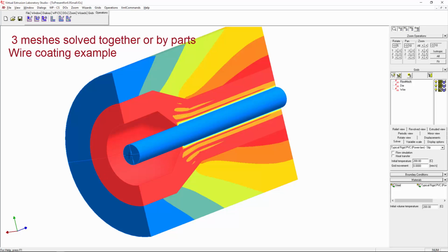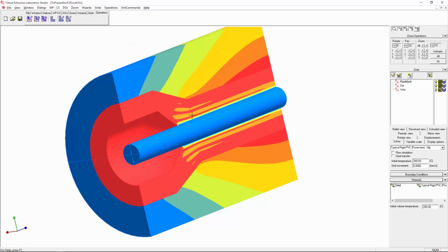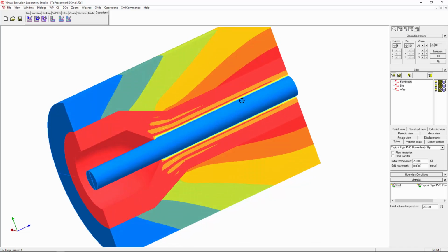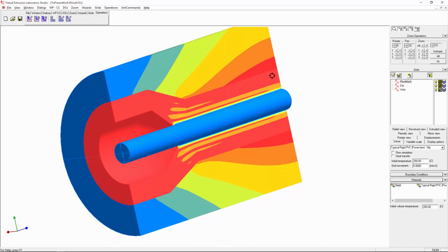Many companies preheat the wire, some companies don't. It is also very important whether the wire has a large heat capacity, is moving fast and is big in diameter, or has a small capacity. So whoever wins really dictates the temperature conditions in the flow and in the wire and die system.